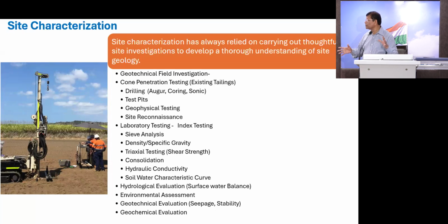What is the difference with sonic? Again, everybody knows coring, because you do coring with rock. Continuously you will core the rock in the subsurface. But in auger sampling, which we call SPT, we do that only every 5 feet or 10 feet depending on the requirements. So in 5 feet or 10 feet you collect a sample through the SPT sampler. But sonic is a method where you can get a continuous sample.